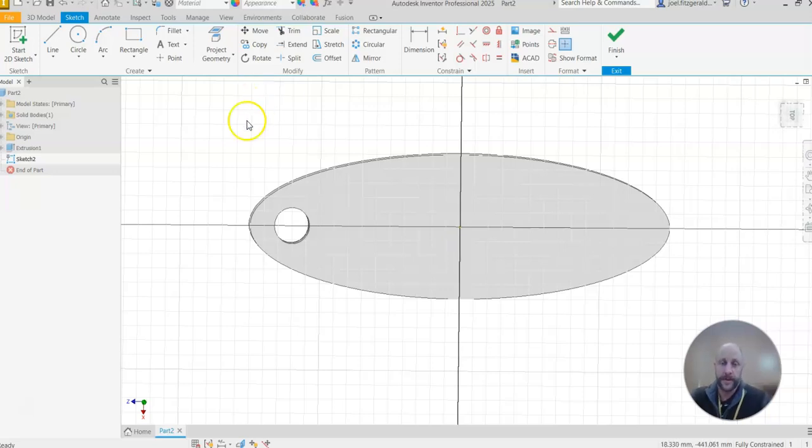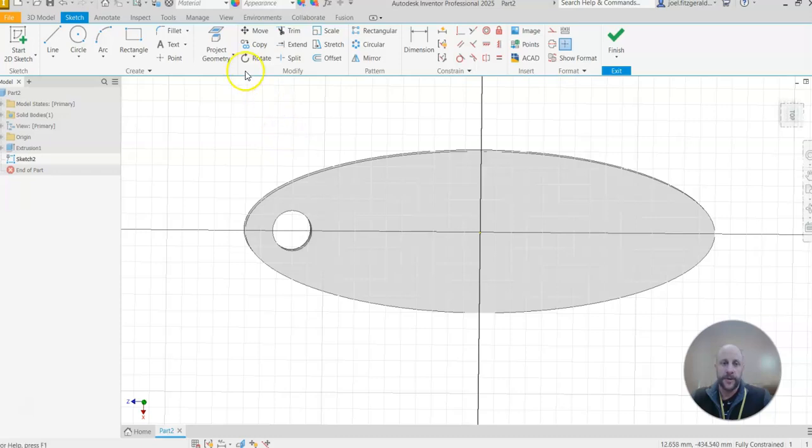All right, next little trick. What we're going to do is create what's called an offset in my sketch. Now I've got this line here, the outside, I'm going to do an offset. So click offset and click the outside shape. Oh, I can't choose it yet. That's because the outside shape is not yet in my sketch. So there is a little icon here called project geometry. This adds an existing shape into your sketch. Project geometry. Click on the outside. And I'm going to also add in my circle. That's going to add those two into my sketch.